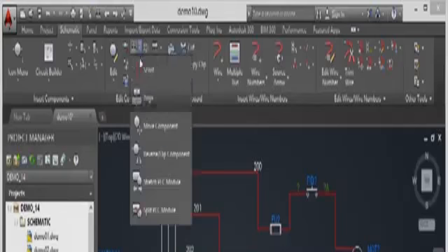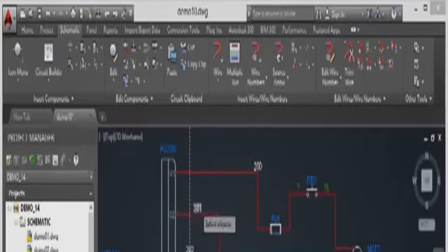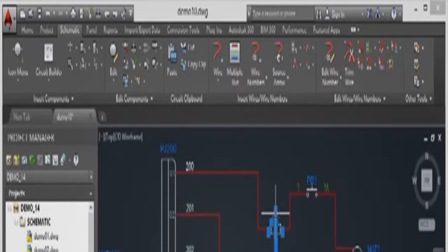We'll go up to the align command here on the edit components panel. There's a line there. I'm going to line it up with this 202 wire number here, and then 201 and 200. I'll just press enter now, and they're neatly aligned. Now you'll notice that this wire here is 200, so that fuse should really represent that wire number.